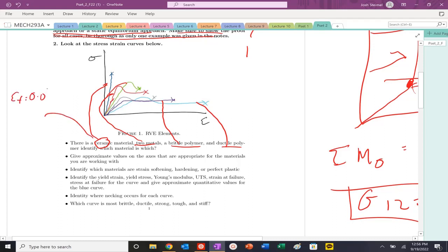So we know ceramics, typically they'll fail at, it varies a little bit, but 0.001 strain values. So remember, ceramics are our most brittle materials. So they aren't going to strain for too long before they fracture. And that has to do with bonding and all those other good things. Compare that to metals, actually.